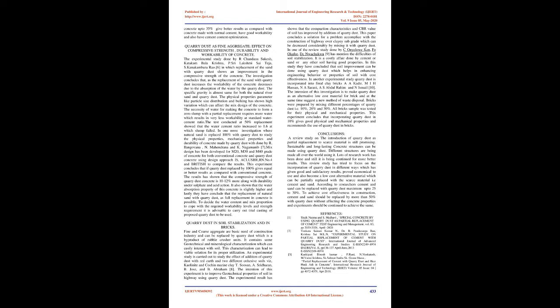In one more experimental study, it was seen that rice husk, which is also a waste material from rice mills, is added in the form of ash with quarry dust as partial replacement of cement content. In this, rice husk ash is added at 5%, 10%, 15% and 20% to the quarry and cement mix by taking quarry dust in variation of 5%, 10%, 15% and 25%.